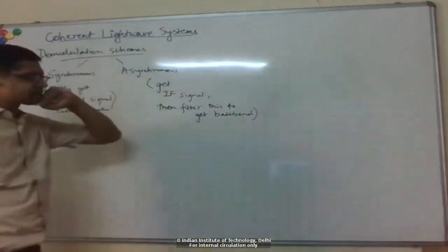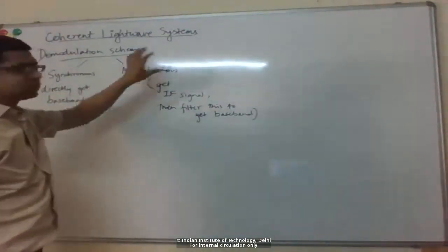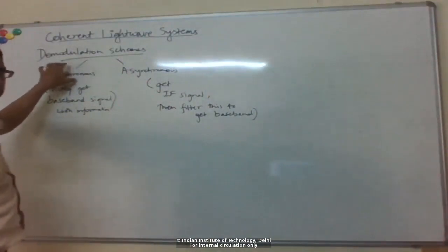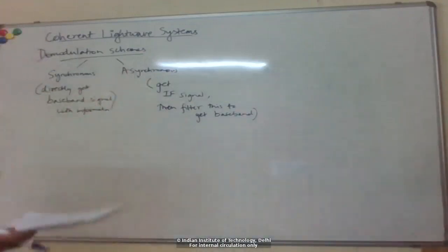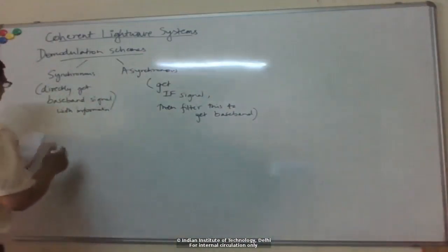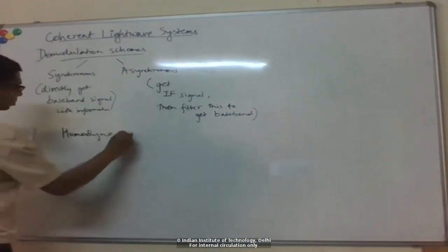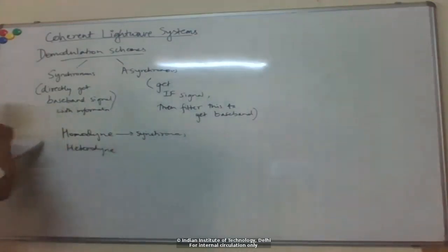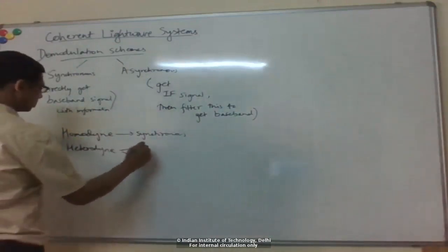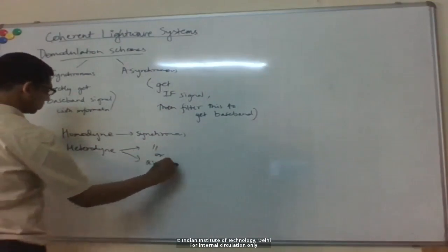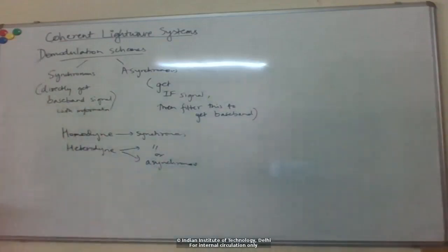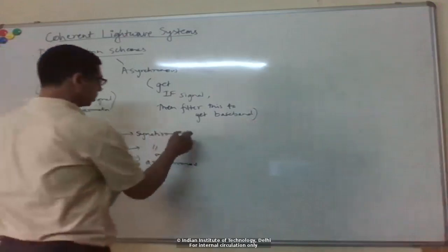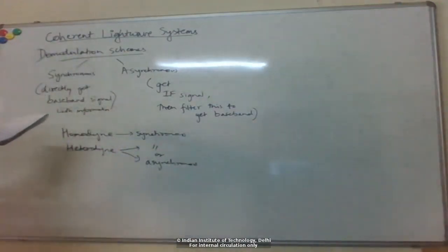Okay, and just like the homodyne and heterodyne case, the asynchronous case is easier and cheaper to implement. The synchronous case has more requirements on the performance of the components that you need, but can give you slightly better performance. So homodyne is by definition synchronous, whereas heterodyne can be synchronous or asynchronous. Okay. So homodyne means synchronous already, and this is just what we discussed already.